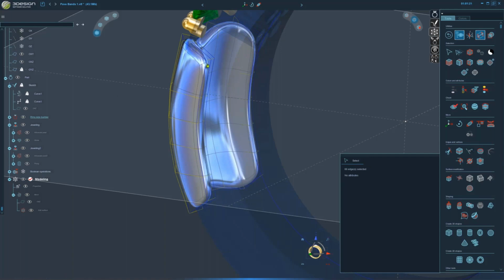Okay. So meshes are soft by default. If there's no sharp edges, you're going to have very soft corners, just like a NURBS curve. When you're doing NURBS curves, you have those corners that are smooth and soft. That's because we don't have any hard points in there. Same idea here. It's a little too rounded, too soft. I want to maybe control that corner a little bit.